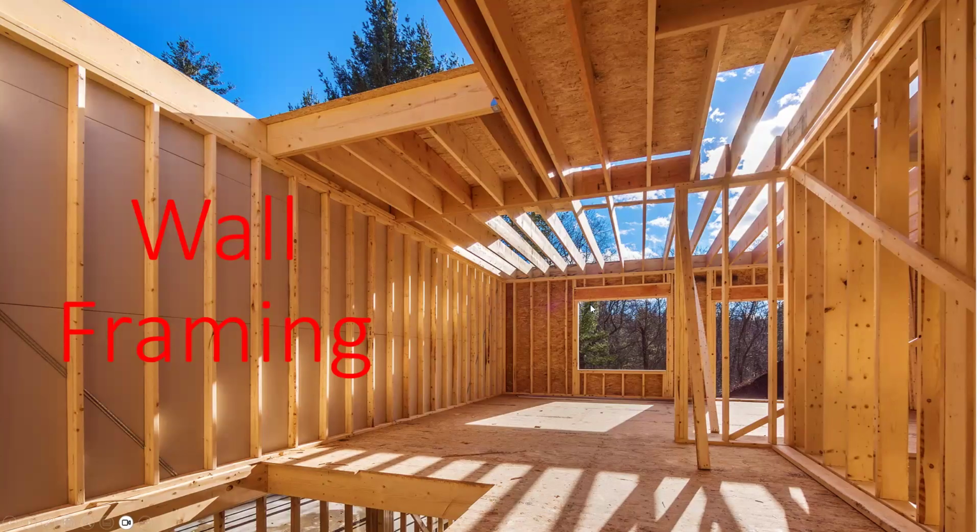The other thing we're going to talk about is lateral bracing. So this has got OSB on the outside, and that provides resistance for the house wanting to tip over. So like if there's a wind blowing on this wall to the left where it says wall framing, that load will get resisted by the ply or the OSB on the wall going in the 90-degree direction, because that will be nailed to the studs and that will try to keep the house from tipping over.